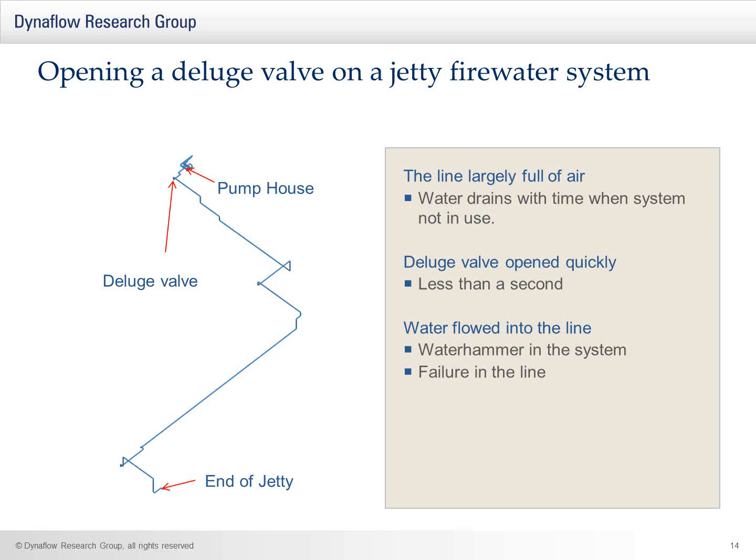When the pump was switched on and the deluge valve opened in the order of 1 second, because the pressure at the discharge of the pump was much larger than that of the gas within the line, the fluid entered the firewater system with a very high velocity of around 10 meters per second. When it reached the end of the system, the fluid column was stopped and a Joukowsky peak passed back through the system, leading to large unbalanced forces on the piping.